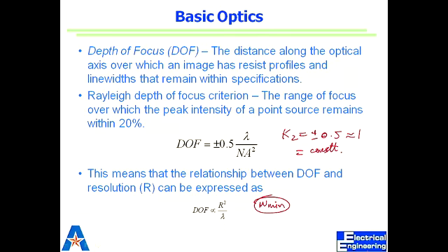So depth of focus is a fairly restricted number, between plus and minus half of lambda over n squared. I think the depth of focus can be controlled by the length between lens and substrate, right? That is a number which is set for a particular wavelength. If we can control the length, that would be much better. We do that to focus it already. But the question is, how far above or below can we still get our registration to work? Of course, we control the distance to focus it to start with.